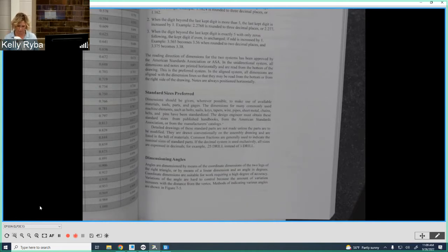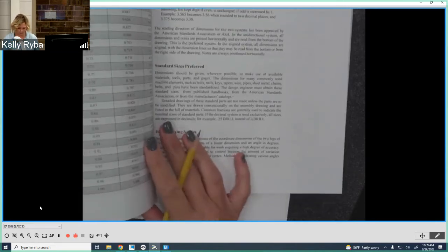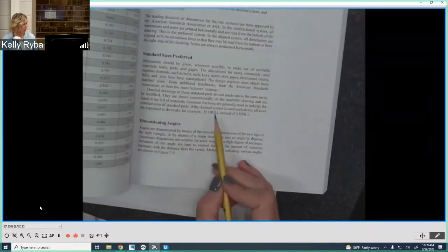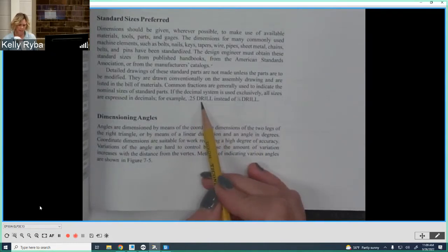You want to call out the nominal size and then apply any tolerance that would be appropriate. Additionally, and this is one of the things where I'm like, no, this isn't quite right. When we call out preferred standard sizes, even though we know there is a 1/4 inch drill, we never put "drill" in back of the size of a hole.